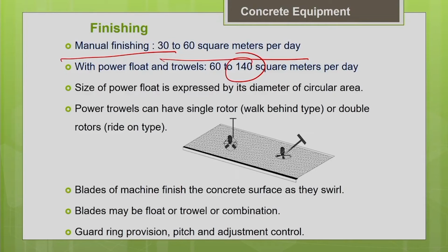So, it all depends upon your project requirements, okay. So, if it is mentioned in your contract specifications that the variation in the undulation levels accepted is very much less, in that case it is preferable to go for finishing machines like power trowels, so that you can have a perfect leveling and finishing, okay.